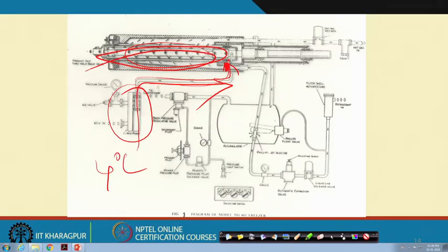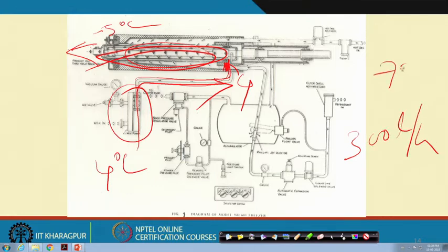Now, this 4 degrees centigrade mix, when it is coming out, is at -5 degrees centigrade, right, and it is continuous, as we said, 300 liters per hour say or 700 liters per hour. That means every hour 700 liters of ice cream is being formed. So, when it enters here at 4 degrees, by the time it comes out from the exit, it is at -5, a semi solid or flowable composition.